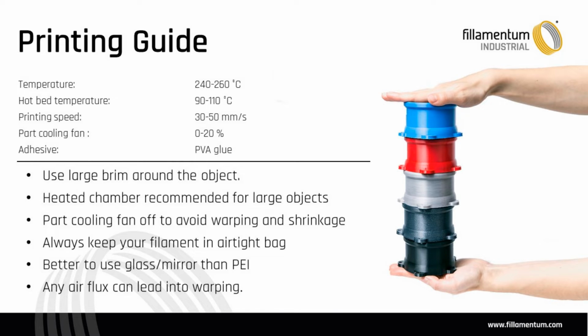What is really necessary with nylons, also with polyamide-based filaments, is to keep them in airtight bags. Proper storage is really important because nylons are generally quite hygroscopic, so they absorb lots of moisture from the air.